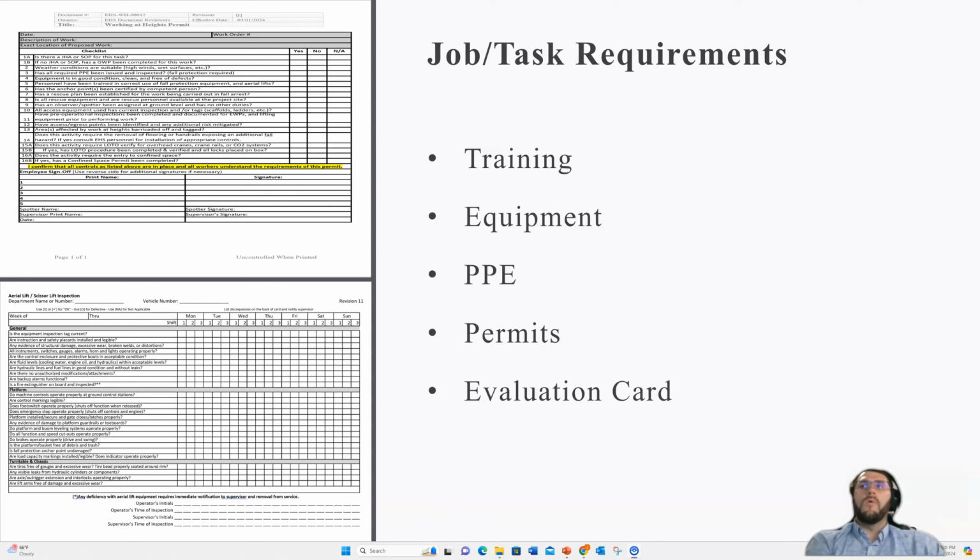This task will also require a 45-foot JLG, which we already have positioned behind the maintenance shop here, barricade stanchions and barricade tags, and a 6-foot fiberglass safety retrieval device in case an accident does occur during isolation or re-energization of electrical energy.